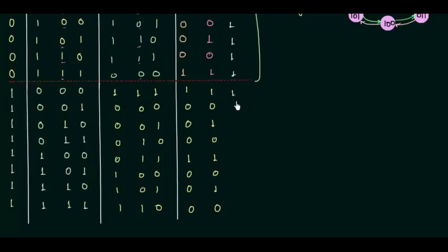And for TA we will have toggling for all these 8 cases, so it is high. And in this way we have completed the table, the circuit excitation table for 3-bit up down synchronous counter. And this part is for down counting.